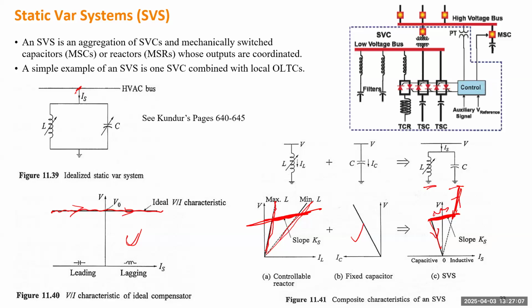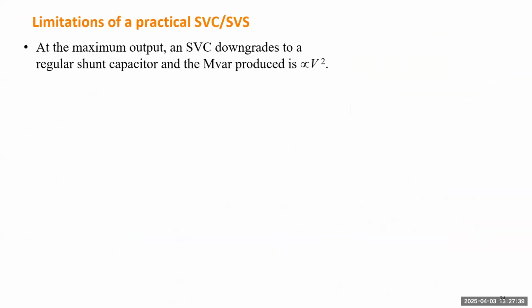Just imagine you involve this system in your automatic control, and under normal conditions, the voltage will be very close to the nominal value. But sometimes it reaches the limit, and you don't know. If you apply further control, it will suddenly drop. That can be very bad if you have a large disturbance, especially a short circuit near this controller. The voltage can be very low, and it cannot give you the rated power you want.